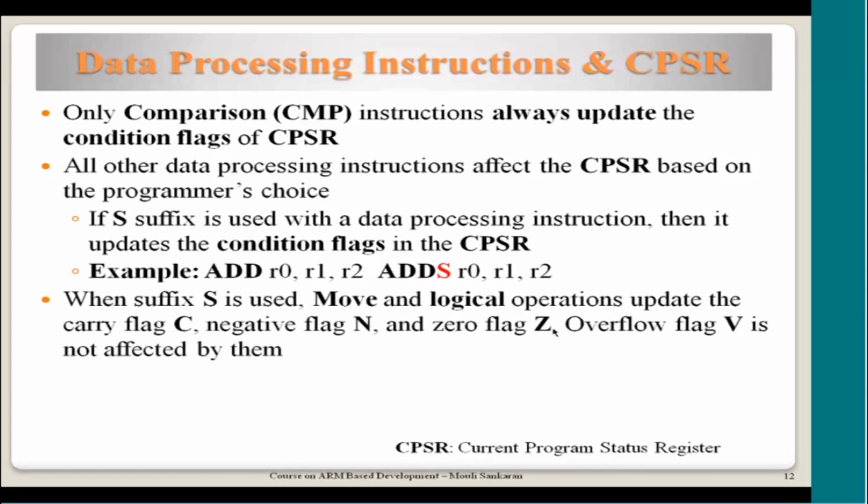Now, how are they affected? It's not only to do with arithmetic operations. Even logical operations, rotate, move, logical shift, or anything can affect the flags. All of them will affect the flags only when you have a yes associated with those instructions. So this is the way they affect. These are the flags that get impacted.